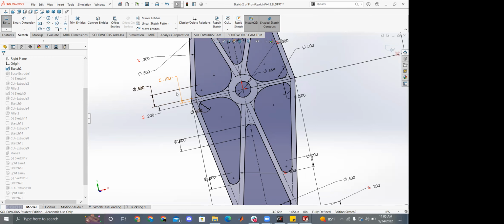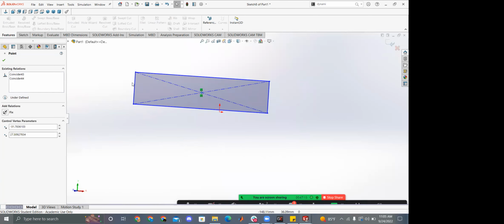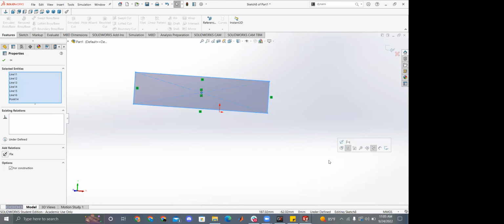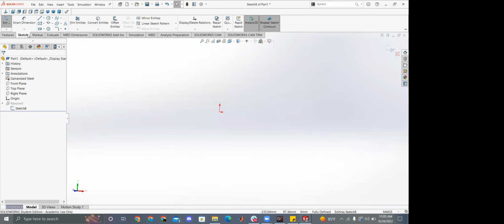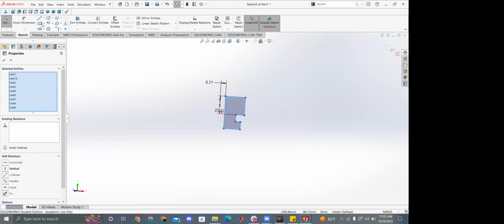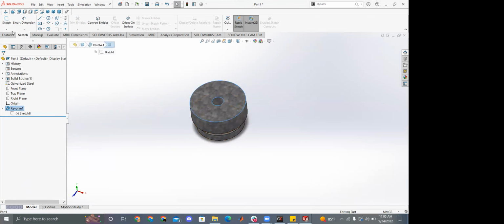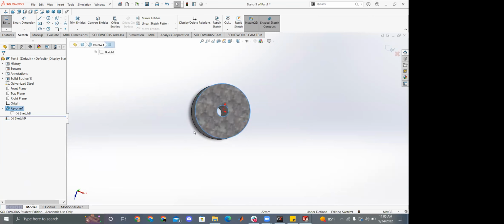Well, similar to mirror, underneath mirror you have linear pattern and stuff. You can do linear patterns in sketches, but editing them can also be annoying, so if you want to do a linear or rectangular pattern, I would recommend doing that outside of the sketch, because it's a lot easier to edit. Are linear patterns in the sketch that bad? Yeah, they're super annoying. I prefer to do that.